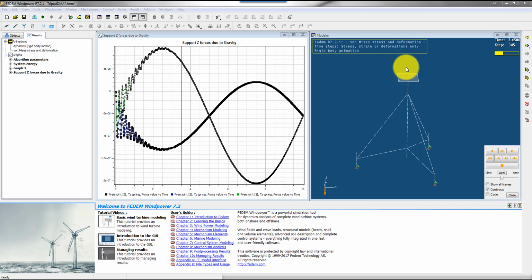What you need to be careful with is to change the triads. That means the supernodes in Fedem. You can't change anything really. If you by accident delete one of the free joints here and you also delete the triad, you have to import the model again in Fedem, because then there will be no correspondence between the reduced superelement matrices from NX and the Fedem model that you see here. So you have to model with care when you use externally reduced models.